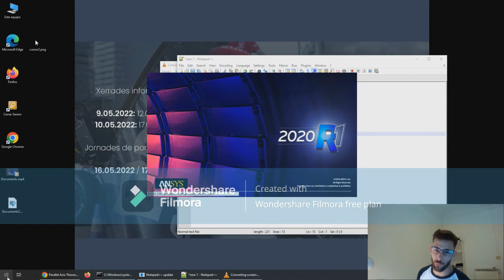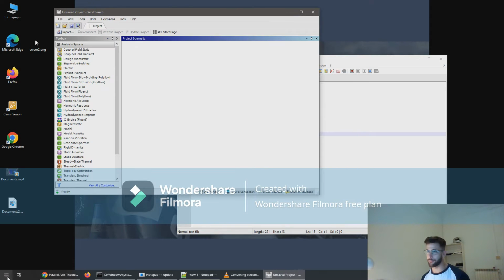Okay, so here we are one more time. We just did the geometry definition, and now we're going to go for the hydrodynamic parameters that we're getting thanks to the frequency domain analysis, right? In this case, we're going to use Ansys Aqwa, as it's valid for the Politecnico di Torino solution and also for the WEC-Sim solution, okay? So the first thing we want to do is go for hydrodynamic diffraction.